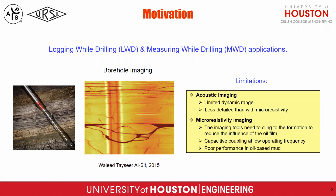It works well in the water-based mud scenario, but its performance is bad in oil-based mud because the oil has very high resistivity, and the electric field cannot penetrate the oil-based mud. And also in low frequency, it has capacitive coupling. So to address those issues, we propose a new sensor design based on the SIW cavity resonator.